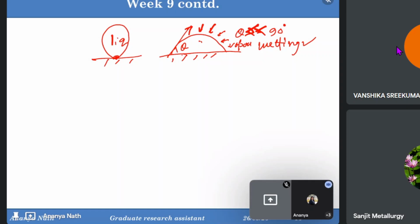Then metal coating on ceramic particles, like Ni coating, may also help. The exothermic reaction between the liquid aluminum and the metallic Ni film forms NiAl3, which will again help in our metal matrix composite formation. The high temperature of the exothermic reaction eliminates the oxide layer. So dissolution of SiC and formation of Al4C3 is prevented by the Ni coating. So as I said, these are some specific examples of the specific type of metal matrix composite of aluminum alloy, specifically with SiC reinforcement, because SiC is the most commonly used reinforcement particle to get the AMC or aluminum metal matrix composite.